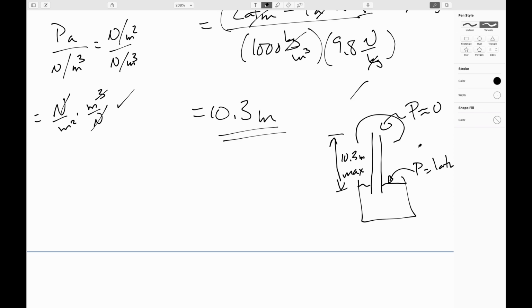So what do we do about that today? It turns out that if you have to sink a depth more than 10.3 meters, the line that's going down to bring up the water also has an air pressure line going down. It's called a jet. What you do is you pressurize the water in the immediate vicinity so as to increase the differential pressure, so that you can lift the water more than 10.3 meters.